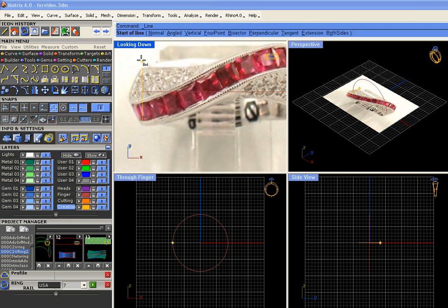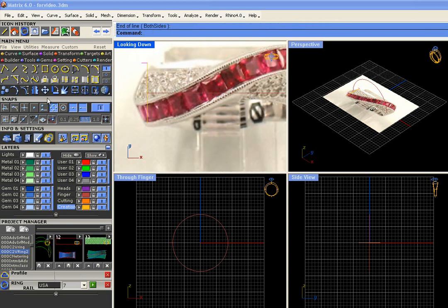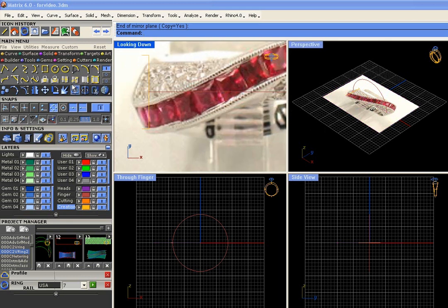Next, let's complete the profile with a small area on the side of the ring, mirroring this. And also with just the point at the top of the ring. Now, a good way to get this is with the point command. Place it right at the quadrant there.